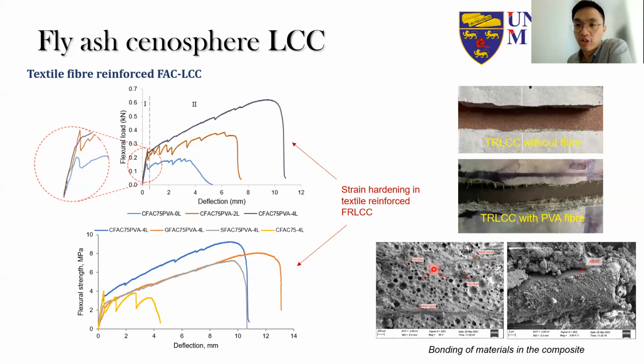so that it forms a network of reinforcement that can actually help to more effectively improve the flexural performance. Because normally when we do not have any fibers in between, the reinforcing is just by each layer of mesh. And when one of the layers fails, the crack will just propagate through and be taken by the next mesh directly. But with the use of fibers, it can delay the failure of the portion in between the meshes, and that is what gives more ductility to the composite.